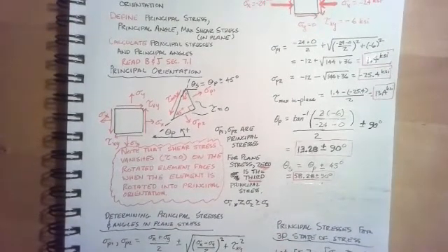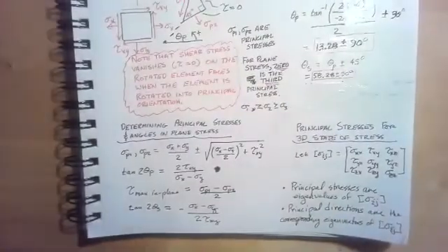So we need to know what these are numerically, because these principal stresses are going to feed failure criterion. And we're going to talk about failure criteria in an upcoming session. So we need to know how to calculate the principal stresses. And if I have a stress element, I can calculate sigma P1 and sigma P2, the two principal stresses that are on the element, relatively easily.